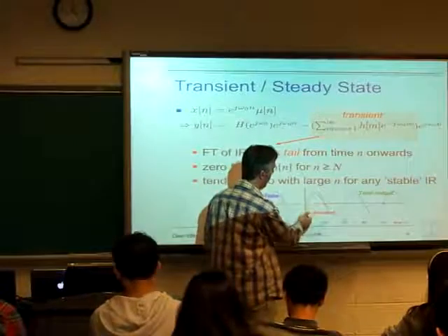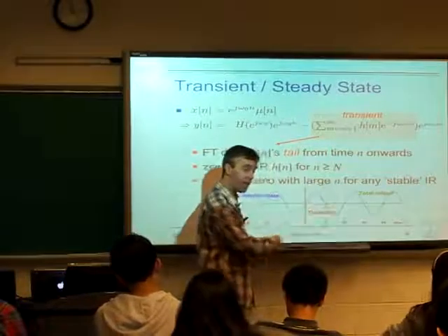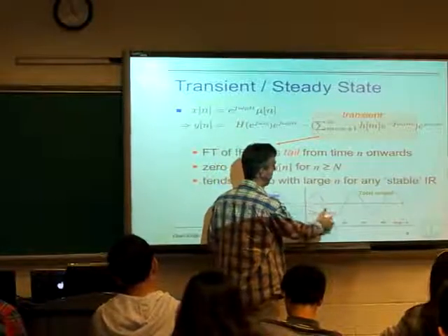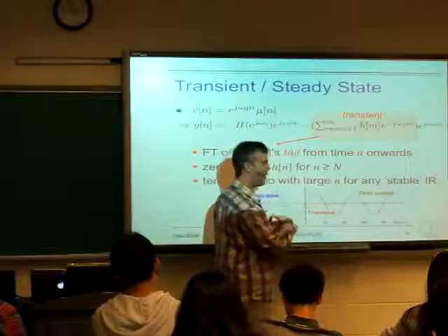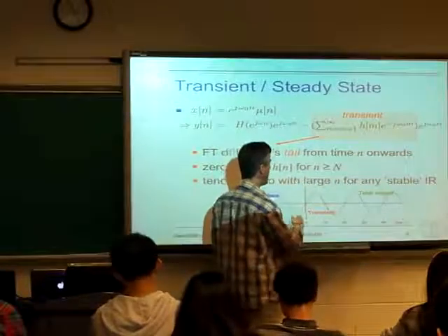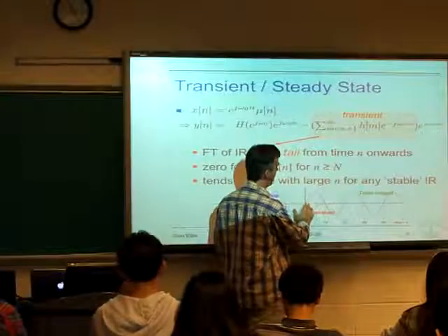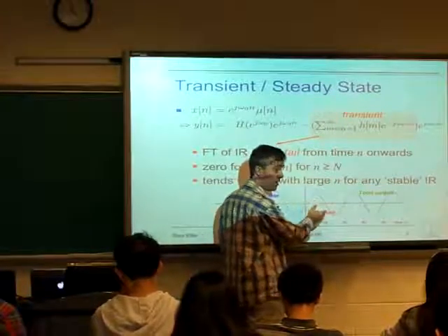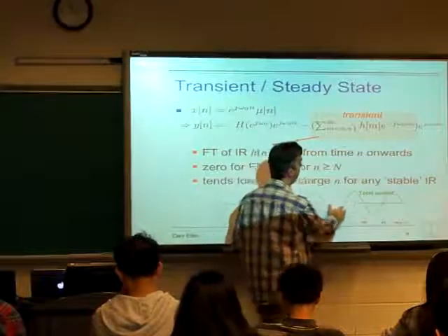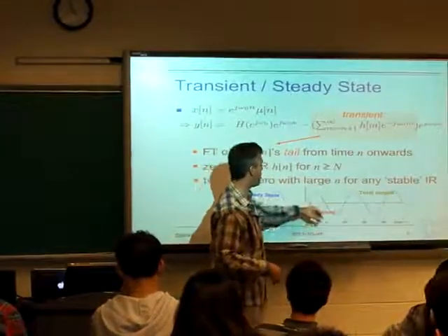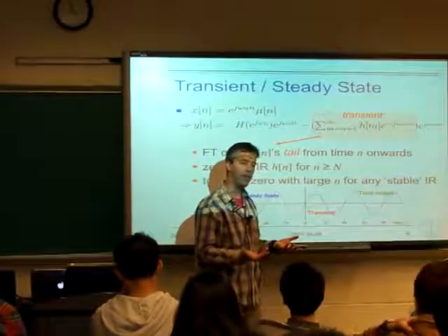And so what we're seeing here is that by virtue of this being a signal that turns on at some particular time, what we actually get is the green. What the Fourier transform view would lead us to expect is the blue. For times close to 0, there's a significant deviation between the two. But as we go on, they become the same. And so this is this idea that there's a transient response, but it dies away.